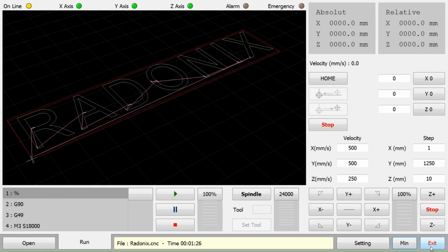If an alarm occurs, a red message appears in the rectangular section at the bottom of the screen, as previously explained, and the alarm light turns red. For example, in this case, the alarm light is on, the X-axis light is off, and you can view the controller's performance report to understand the cause of the alarm. When the report is opened, the reason for the alarm will be identified. The relevant error is related to alarm X.